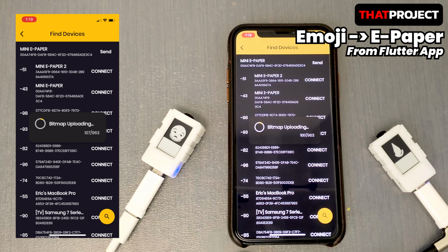It's slow because the file is transferred using Bluetooth LE. Definitely BLE is not suitable for file transmission, but it can be very useful when exchanging data with hardware on iOS and Android, so I use it mainly. The size of data that can be transmitted at once in BLE is 20 bytes. The MTU size can be increased, but I'm sticking to the original size of 20 bytes because problems can occur depending on the device if we change it.